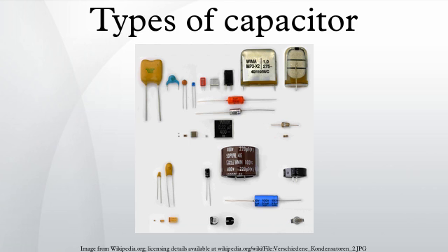To measure these losses, the measurement frequency must be set. Since commercially available components offer capacitance values covering 15 orders of magnitude, ranging from pF to some 1000 F in supercapacitors, it is not possible to capture the entire range with only one frequency. IEC 60384-1 states that ohmic losses should be measured at the same frequency used to measure capacitance.